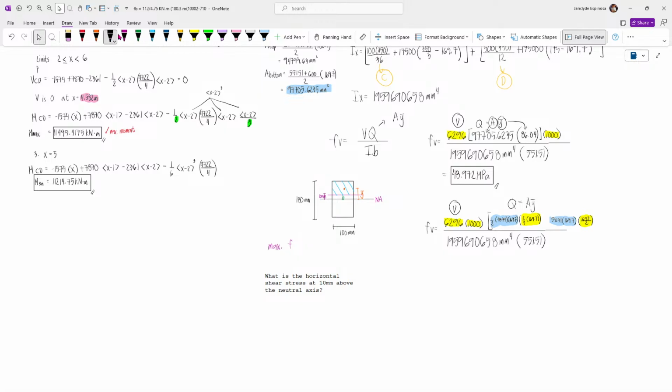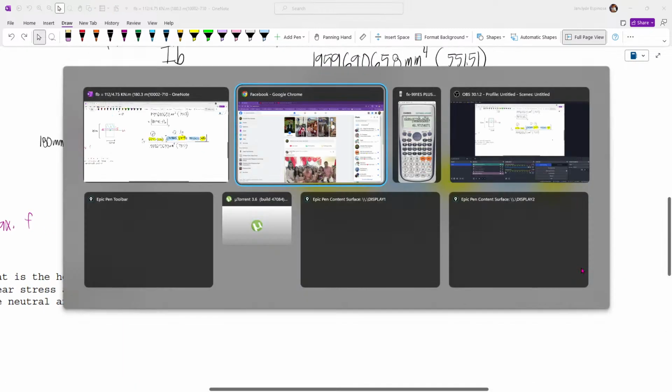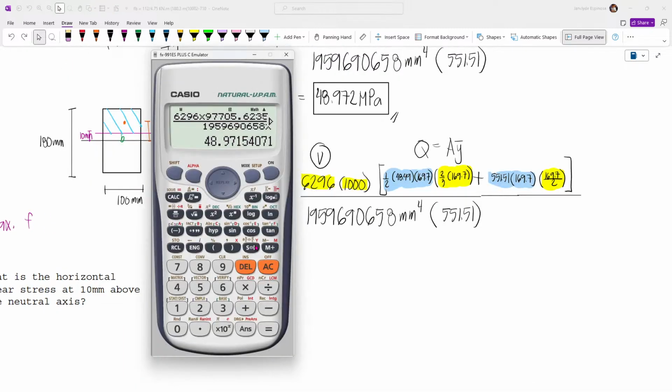And then, we divided this into two shapes, so we add them. If the section is hollow, you subtract. Let's solve to see if the result is the same. So, what remains is our area barred Y.